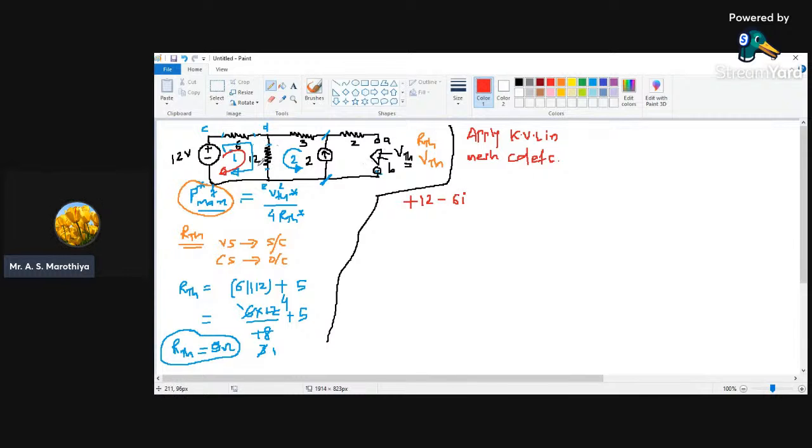And then when we are moving through this 12 ohm resistor, if you see across this 12 ohm resistor, we have two currents. First is through mesh 1, and the direction of current I is downward, and the second one is a current of magnitude 2 ampere, and both the currents are in the same direction, that means downward, that means they are additive, and we are trying to read the circuit in the clockwise sense.